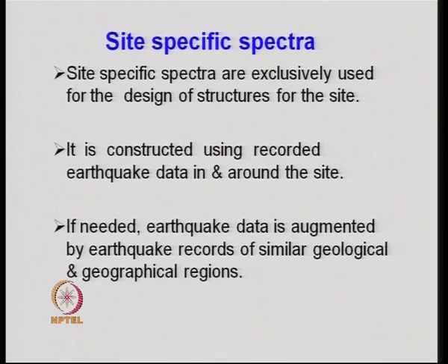Now, for that, what we do is collect as many earthquake data as possible for that particular site, that is in and around that site. Sometimes if the collected data is not sufficient, then we augment the earthquake data by collecting data for similar geographical and geological regions.